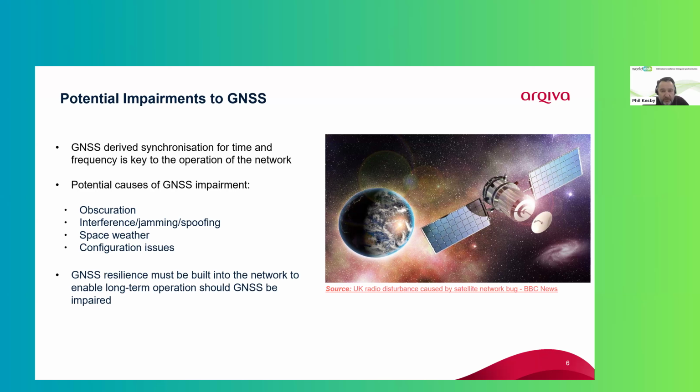We've suffered this sometimes on some of our main broadcasting sites where we have very high power UHF co-sited, and often we've found that we have harmonic issues coming from the UHF services, but because of the VRP of the transmit antenna, we're able to physically move the antenna around the site to reduce the level of the harmonic falling on the receive frequency of the GNSS receiver.